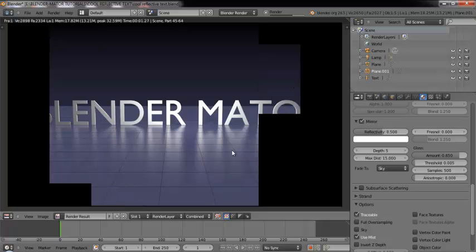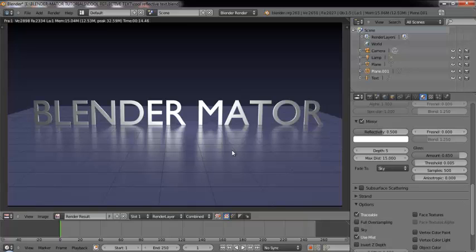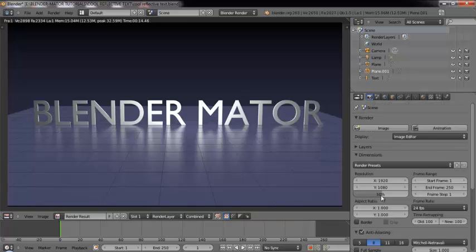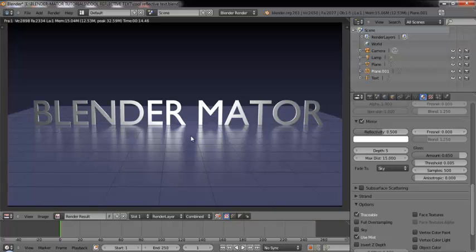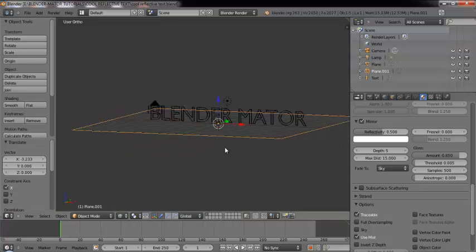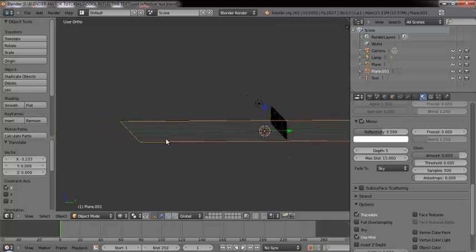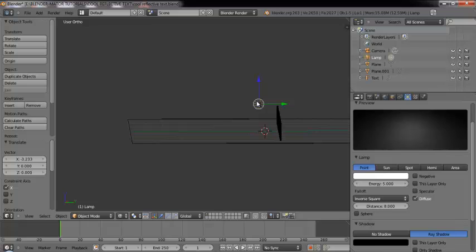Takes quite some time to render as we keep on tweaking values and attributes. Just go to the render settings, and just make sure you're on 50%. We don't need much more than that for the time being. In the final render we can make changes in that, so that the render time is faster and we get quick renders. Okay, samples, let's stick with 500 now, and maybe later on tweak it. Fine. So we have this light here.